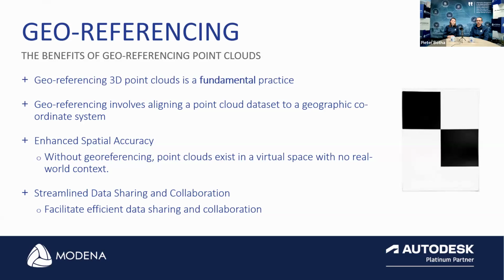So one of the biggest advantages for you would be to get a surveyor out on site for some georeferencing. The benefit of georeferencing is that it's actually a fundamental practice. If you look back at survey measuring over the past decade or so, it's a very fundamental practice that we need to get back to, and it involves a surveyor going out to site, measuring some targets for you, and you placing your point cloud data set over that to check it against the georeference coordinates given by the surveyor.